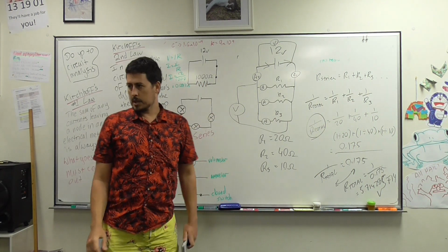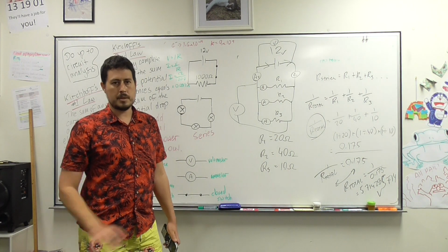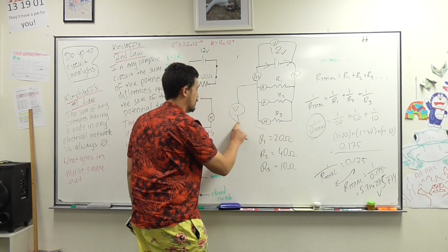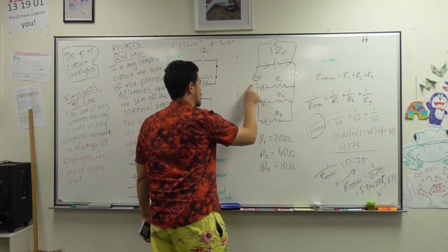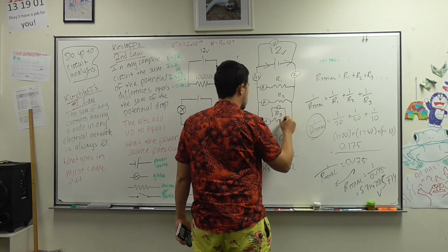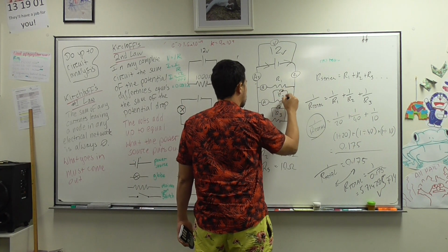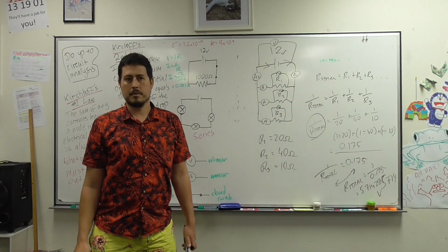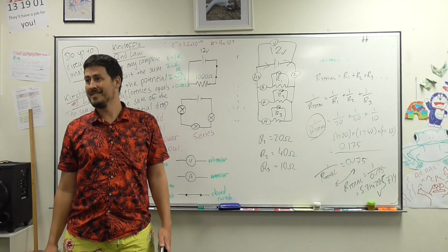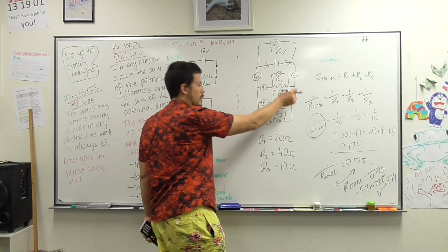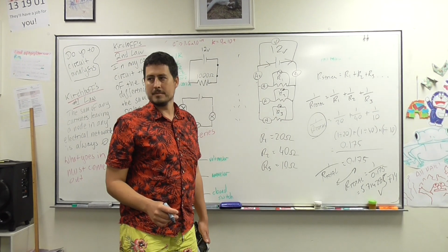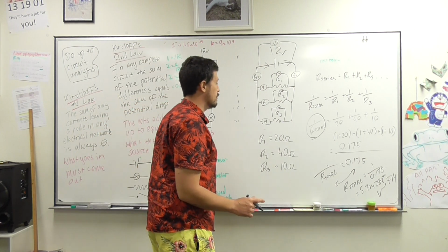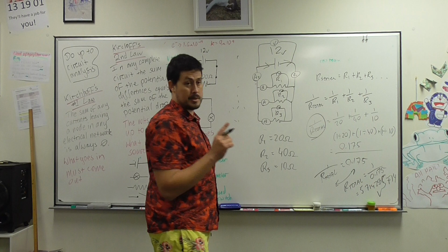What are those voltmeters going to read? Yeah, 12 volts, because they're measuring the load dump across all 3 resistors. But if you independently put a voltmeter across each of these circuits, so we've got a voltmeter here, a voltmeter here, and a voltmeter here, what are they going to read? 12 volts. Yeah, because remember, they're all applied with the same water pressure. I know the way I sounded was like it was going to be different, but it's not. They all got 12 volts. What changes is the current.